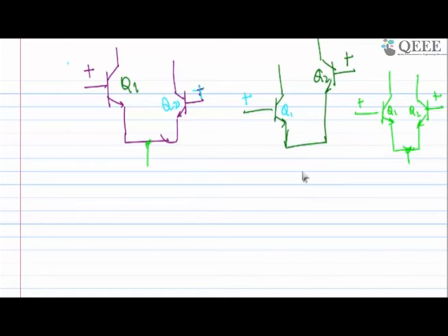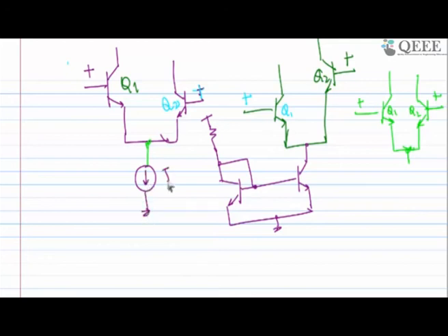To solve this, you have to use a current mirror circuit at the bottom. Unfortunately it's not part of this course, but I'm just drawing it for you. If you can understand, it's good. So this is a circuit you should put instead of this kind of source IEE. This circuit will solve your problem of temperature dependency. The current will not change and your common mode will not change. This is the circuit you should use for answering your question.